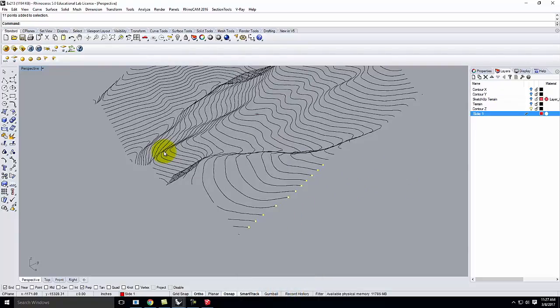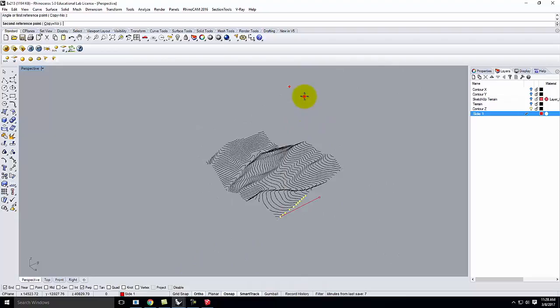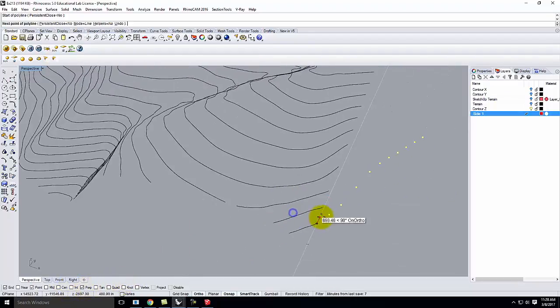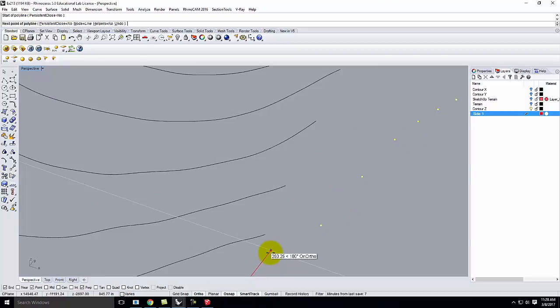Then I'll use Rotate 3D. And I will rotate from being vertical to being horizontal. Turn on my point snap, and then go ahead and draw the steps. I should turn on perpendicular as well. Good, it already is. And we can go ahead and work our way through.